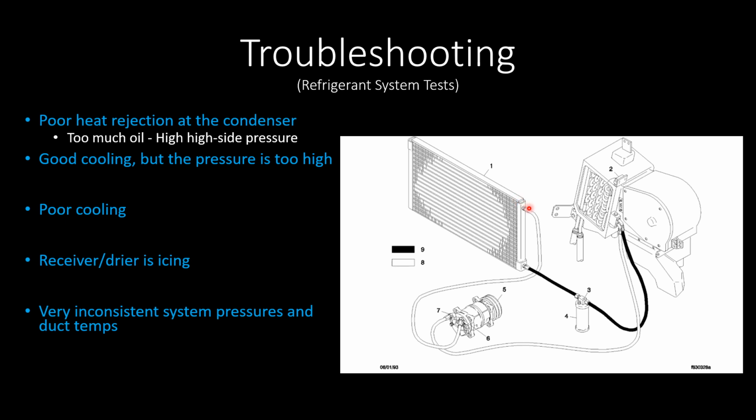Now, that's one thing I failed to mention throughout the lecture, which was the oil. We talked about the refrigerant when we were discussing the 609 certification, but I didn't discuss the oil. So this system has oil in it to keep the compressor lubricated. That's the primary purpose.